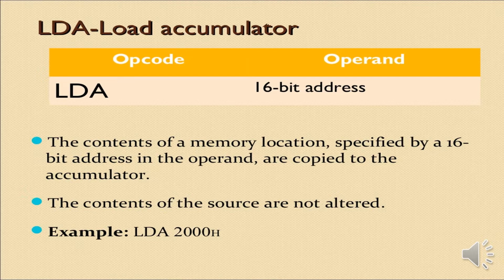In load accumulator, the A register is an 8-bit register. The content of the memory location specified by the 16-bit address in the operand is copied into the accumulator. The content of the source is not altered.